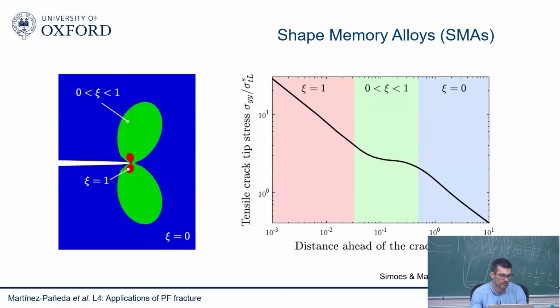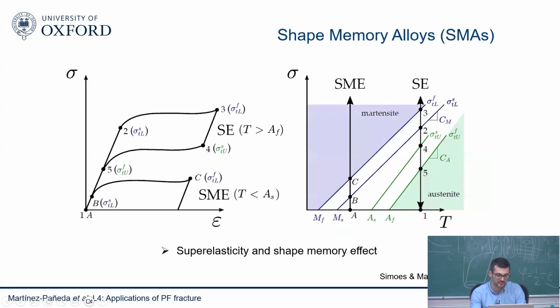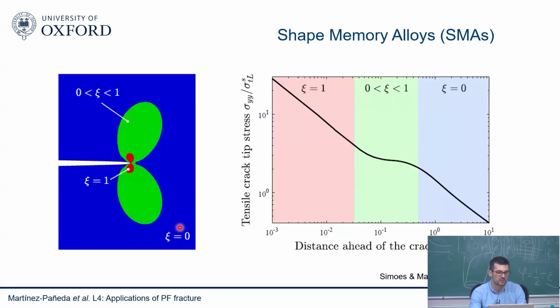Yeah, so this is what it looks like. You can see here, this is the martensite phase fraction variable. It's equal to 0 in the austenite region, then it becomes between 0 and 1, and then it becomes fully 1. So this is a state variable. Again, you can use phase field to model this phase transformation too, but we're only going to model cracks for the time being.